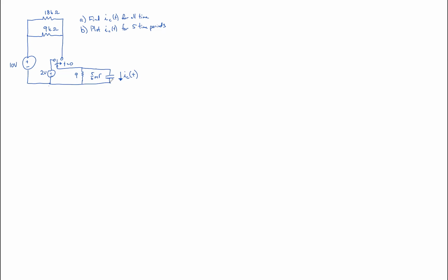So let's begin. First step in analyzing this is to ask, what method are we going to use? Since it's problem 1, I've already told you we're going to use first order circuits. But if I didn't tell you that, you'd take a look at it and say there is only one energy storage element, and it's this capacitor right over here. So we know there's going to be some time varying component to it, but we only have one capacitor.